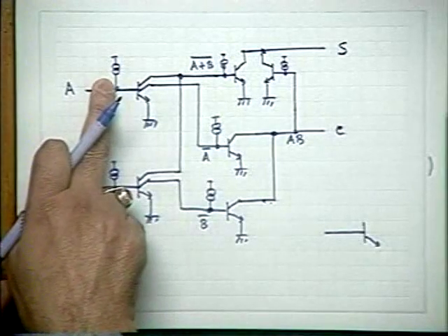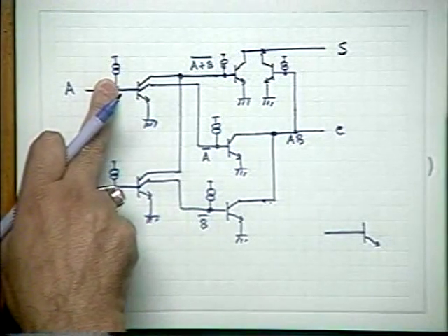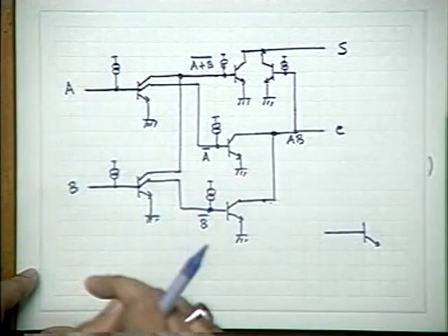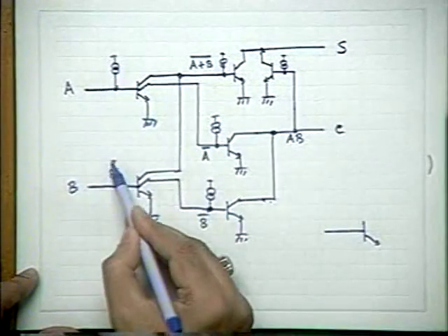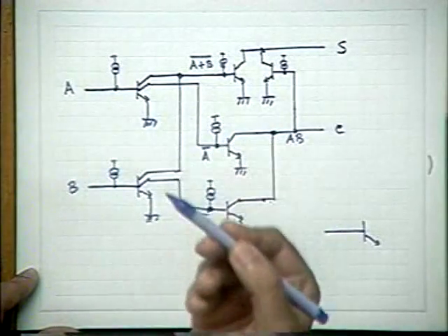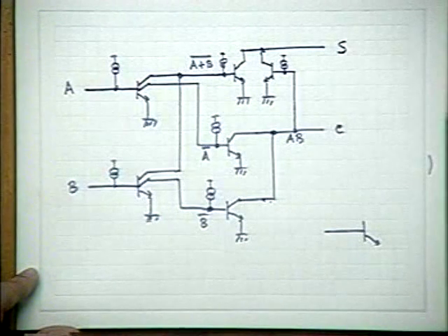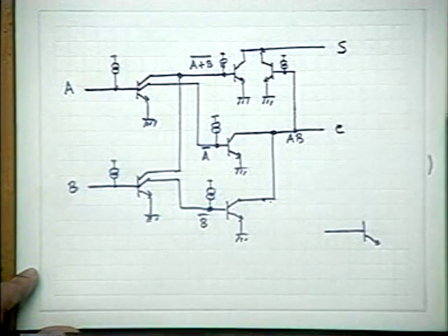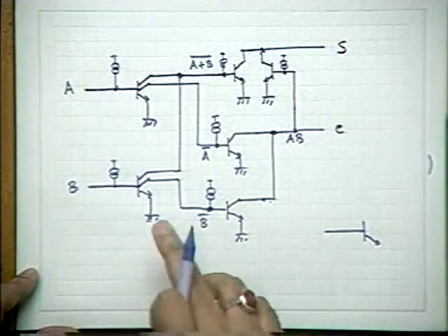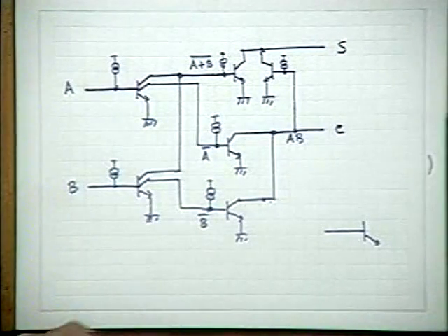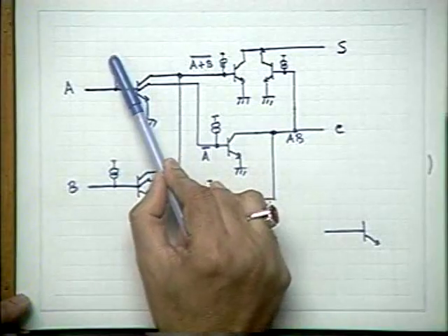This injector, what is this? What is the symbol for this? It is a constant current which is supplied by the injector. What is the significance of these lines? Some supply. Maybe it should be a constant current supply and not a voltage supply. Please remember, that means you have to take a voltage source, and in series with that you have to put a resistor. Then only you don't connect directly a VCC kind of thing here.